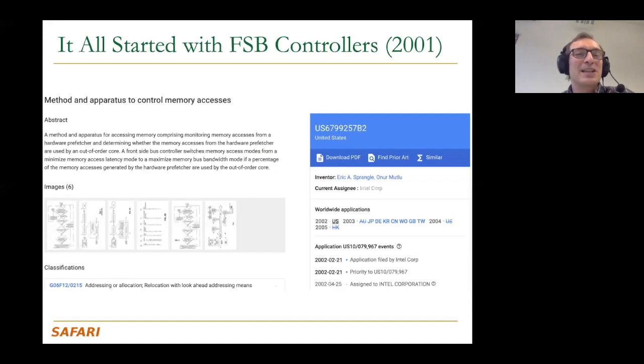If you want to reduce the memory latency, and your memory controller is on a separate chip, now you go from the processor chip to the memory controller chip first, which adds latency, and then you go from the memory controller chip to memory to schedule requests. So this adds latency to the entire memory access, which is terrible. And you have the integration capability to put the memory controller on chip and get rid of this memory controller chip, basically. And that's essentially what AMD did. And after AMD did it, Intel had to do it also because AMD showed you could actually cut one third of the memory access latency by getting rid of this truly unnecessary memory controller chip from the system.